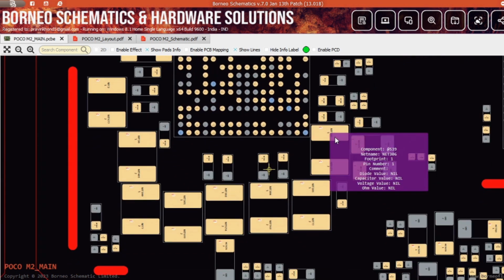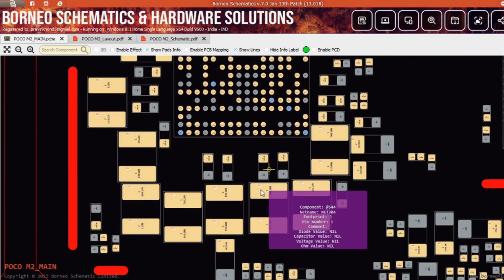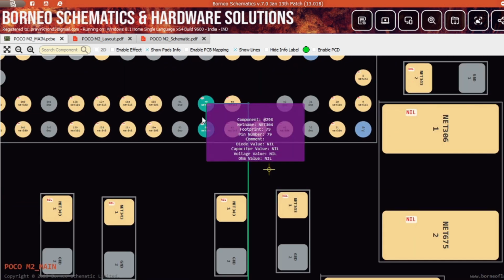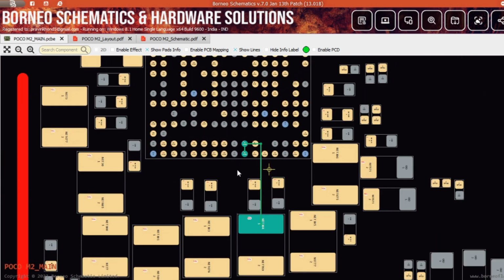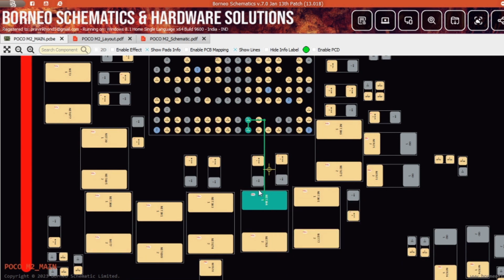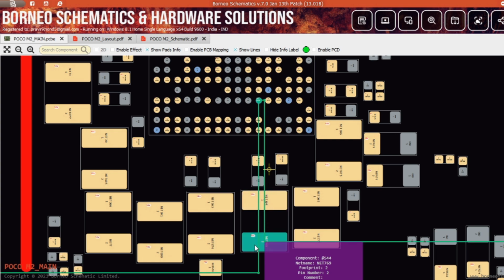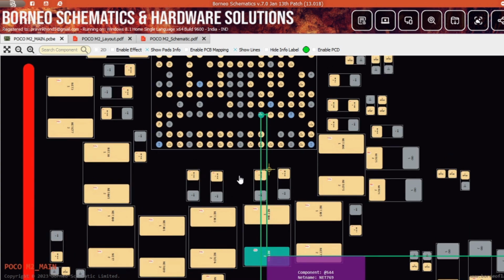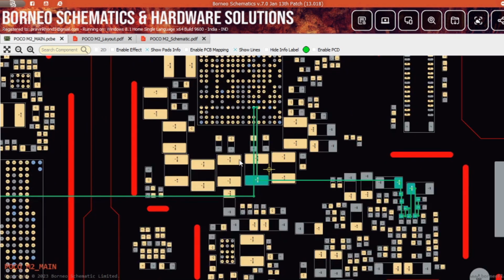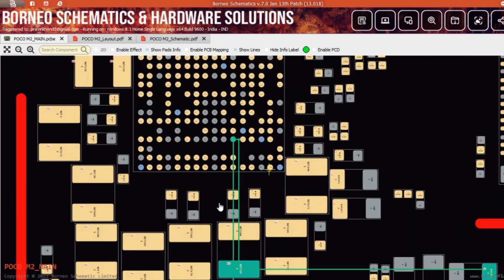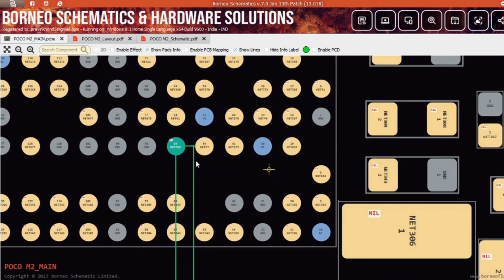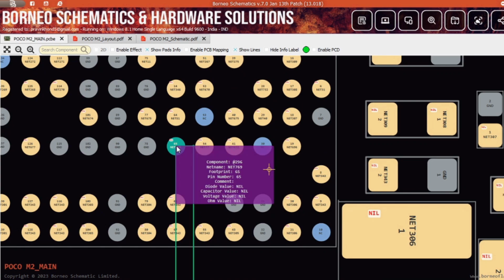Now coil number three, you will see this. We are talking about this coil. Now when you click on this input side, you will see these two pins are two wires from the power IC. This coil is connected and switching here. After the switching, on the other hand, this line goes to these capacitors, and also goes back to the power IC, the power chip, with this port we call a feedback.